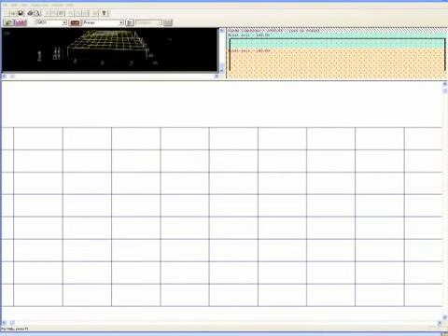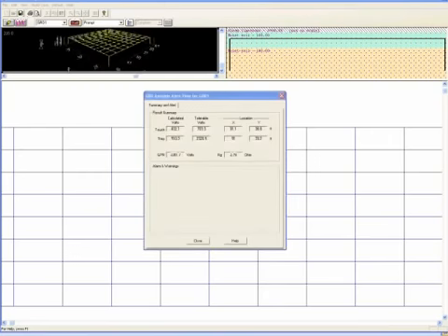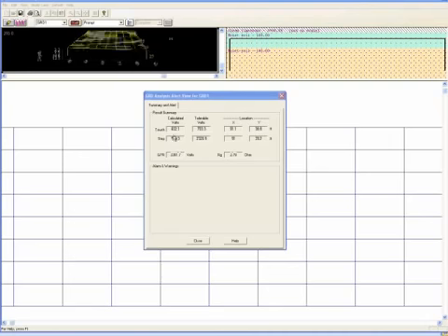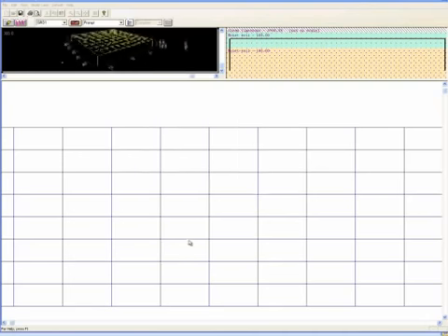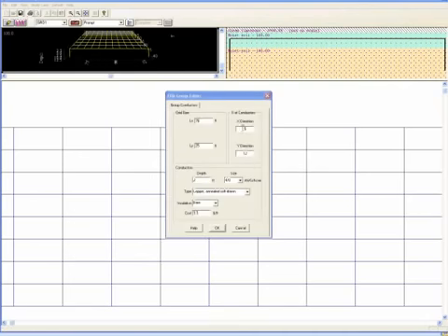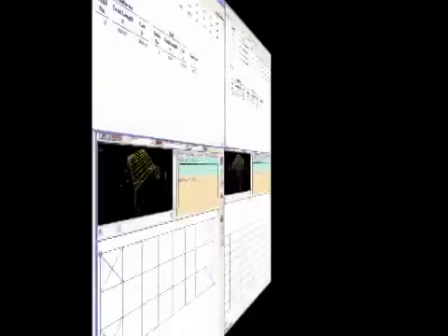Alternatively, the IEEE method could be used. However, according to the standard, the conductors and rods can only be added to the whole grid uniformly. In this case, an equivalent design with maximum voltage drop similar to FEM solution would require a total of 8 more conductors at both X and Y directions.